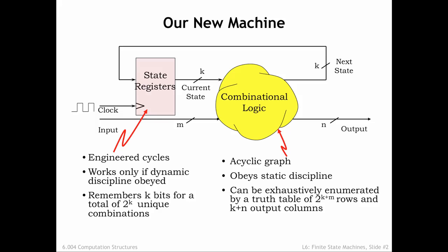To the extent that previous input values influence the operation of the sequential logic, that happens through the stored state bits. Typically, the load input of the state registers is triggered by the rising edge of a periodic signal, which updates the stored state with a new state calculated by the combinational logic.